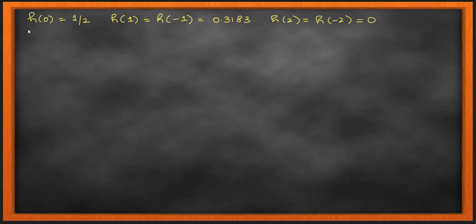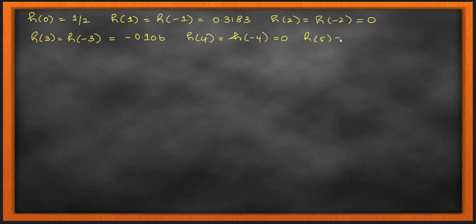So I want to make it causal. What I'm going to do is multiply it with z to the power of minus m minus 1 by 2. When I do that, I'm shifting this entire signal from -5 to +5 to 0 to 10. Yes, that is exactly what will happen. So I'm just shifting the signal by multiplying it with z to the power of minus m minus 1 by 2, and then I get coefficients from h0 to h10, and that is your FIR representation.